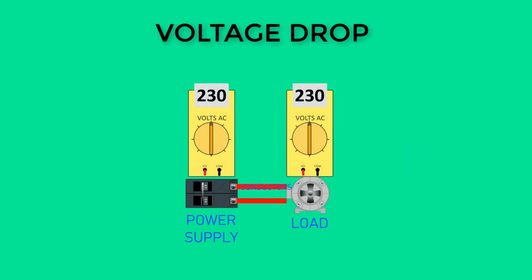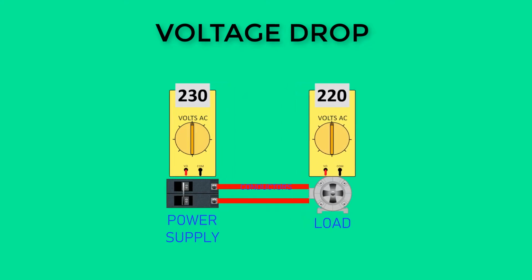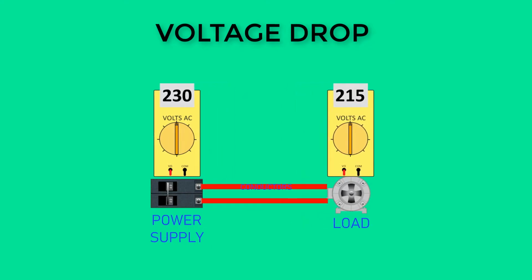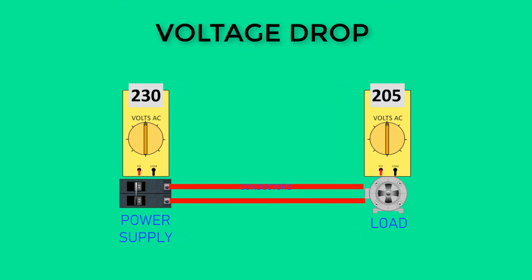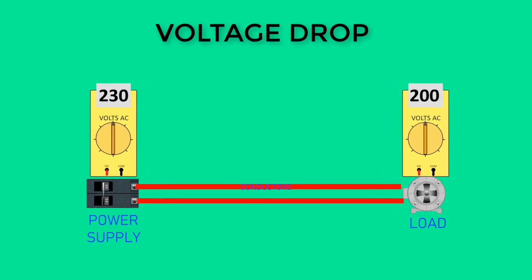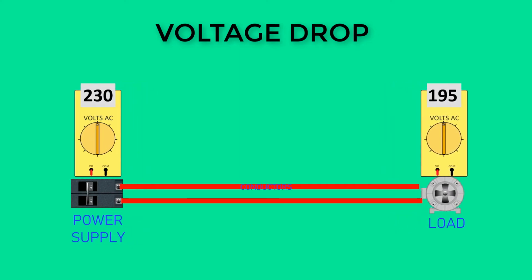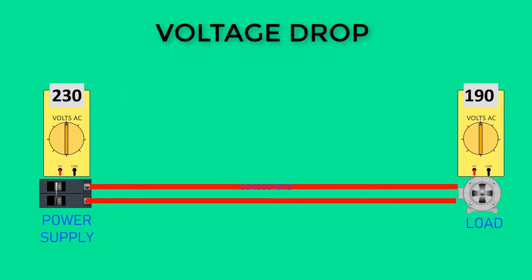Excessive voltage dropped in conductors will result in a low voltage at the electrical load. Low load voltage may damage or destroy electrical equipment. The distance between the source voltage and the electrical load may need to be considered when designing circuits. Excessive distances will result in large voltage dropped in the conductors and low voltage at the load. Calculating voltage drop will assure that the correct conductors are used to prevent excessive voltage drop.